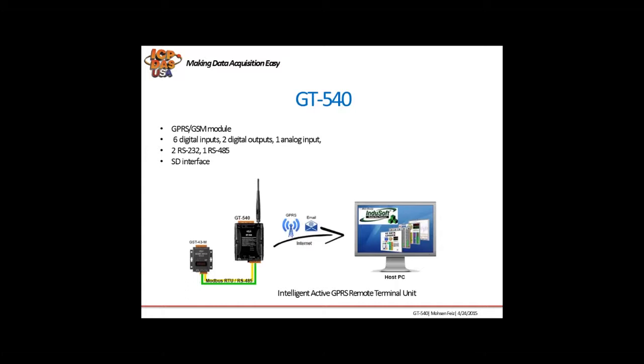It comes with 6 digital inputs, 2 digital outputs, 1 analog input, and it has 2 RS-232 ports and 1 RS-485 port for further communication at the other side for a Modbus RTU network. It also has one SD interface, which can be used as a local data logger.